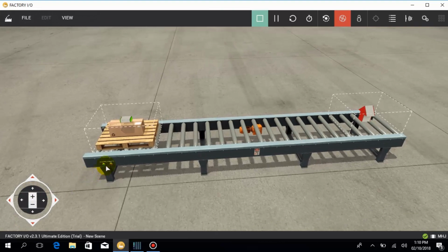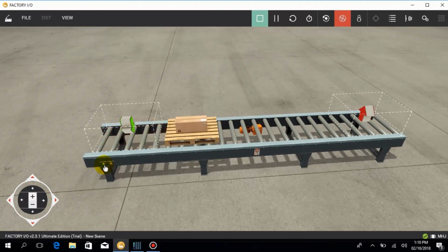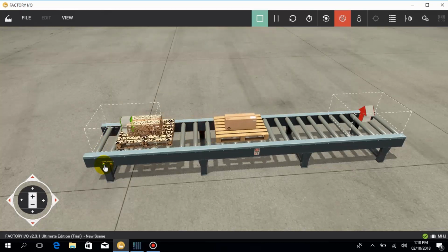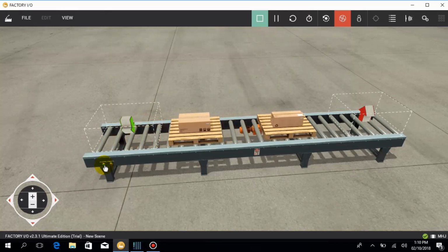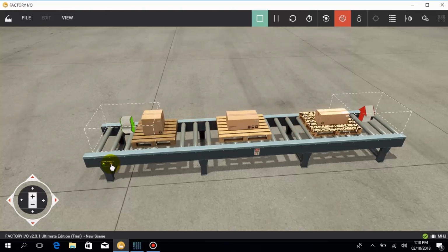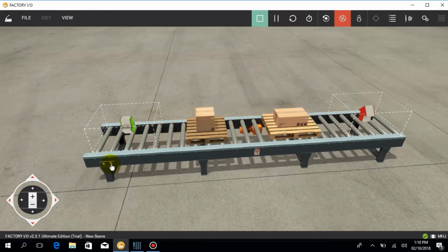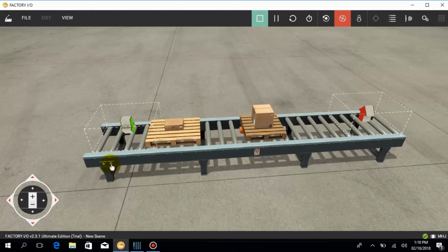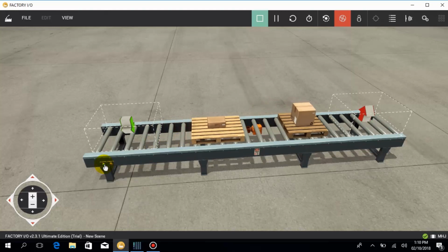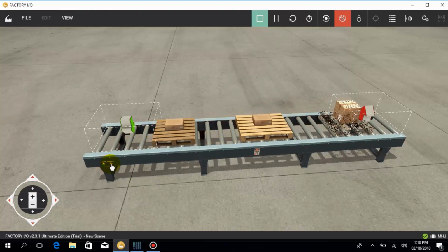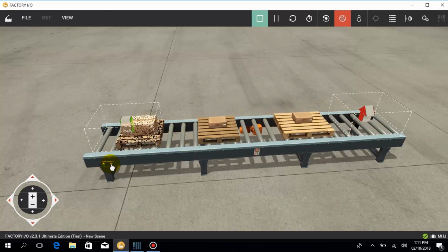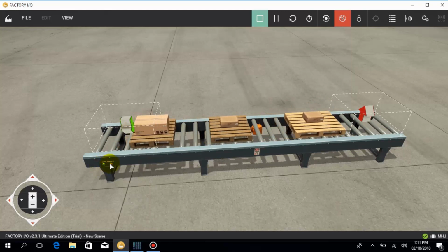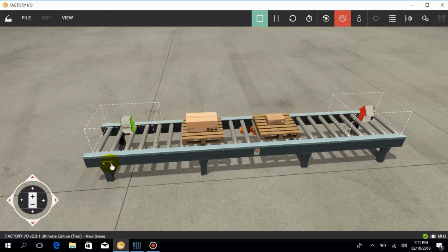Okay, when I press the start push button, the roller conveyor starts and it is latched. When I press this stop push button, it directly stops the conveyor like this. When I press start again, it latches the conveyor, and when I press the stop push button, it unlatches. So that is easy.